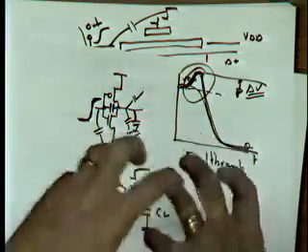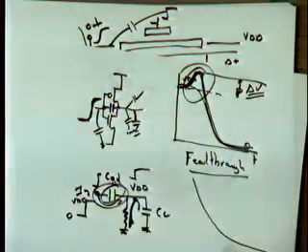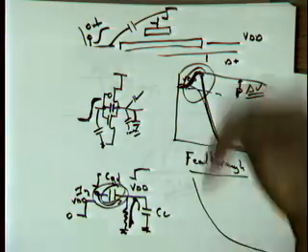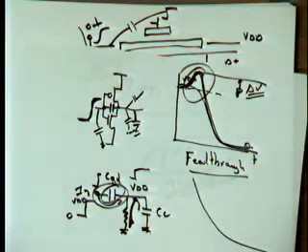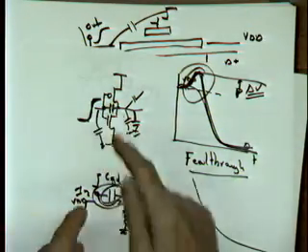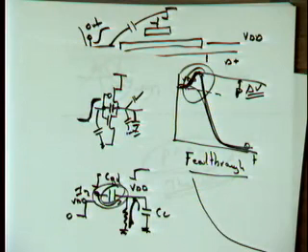But most of the time, your load capacitance is going to be much bigger, right? You have all this fan-out, diffusion capacitance, wiring capacitance, connected gate capacitance. All those things are sitting there. And this thing is almost nothing else than overlap capacitance. So the ratio is going to be small, so the little hop is going to be quite small.